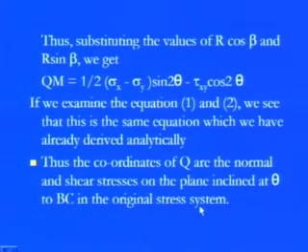That means we can say that even after rotating by 2 theta, the coordinates are nothing but sigma x and sigma y if the normal stress is in the x direction, and the tau xy. This is the same. It's a combination of normal as well as shear stress in a plane stress condition, and theta is always the angle made with the BC of this particular plane.